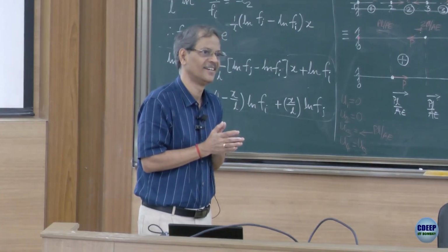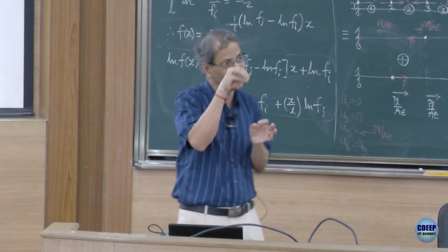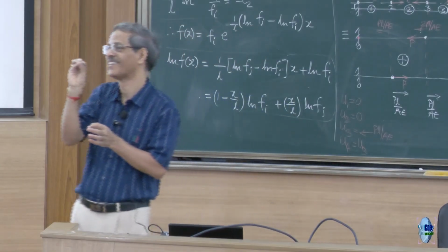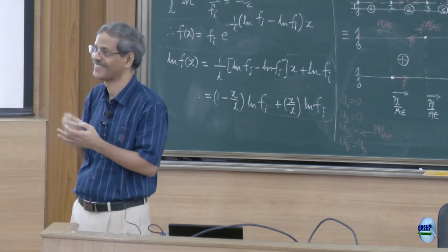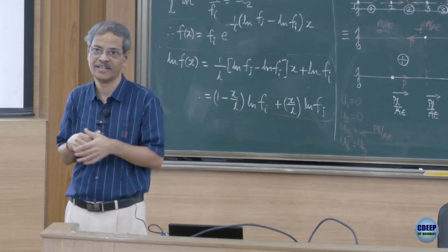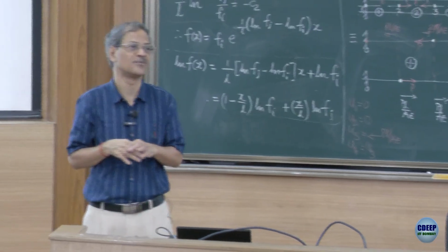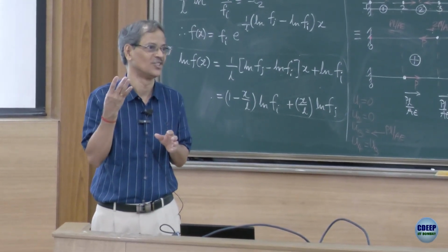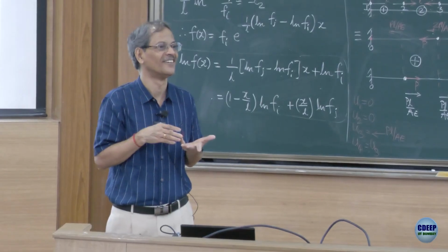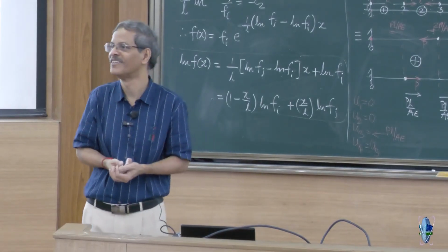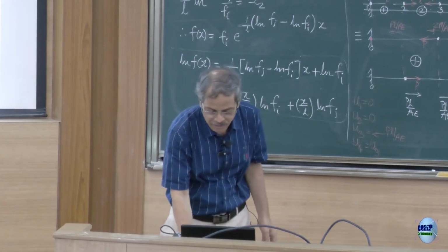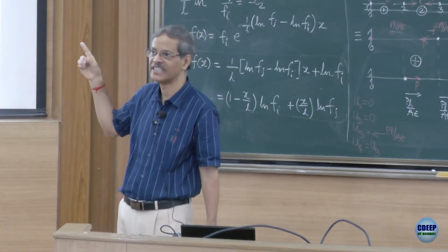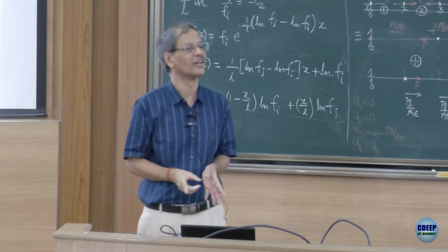right? But when I substitute the coordinates of node 1, which is minus 1, minus 1, correct? How much has it become? 4. So, I want it to be 1. So, what should I do? What did you get? 1 minus zeta into 1 minus eta divided by 4.